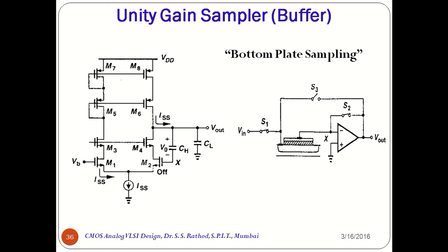The tail current of the op-amp's input differential pair is then steered to one side, and its mirror current charges the capacitance CL at the output. Since M2 is off during the slewing, Cin capacitance is negligible and the slew rate is approximately equal to ISS by CL.